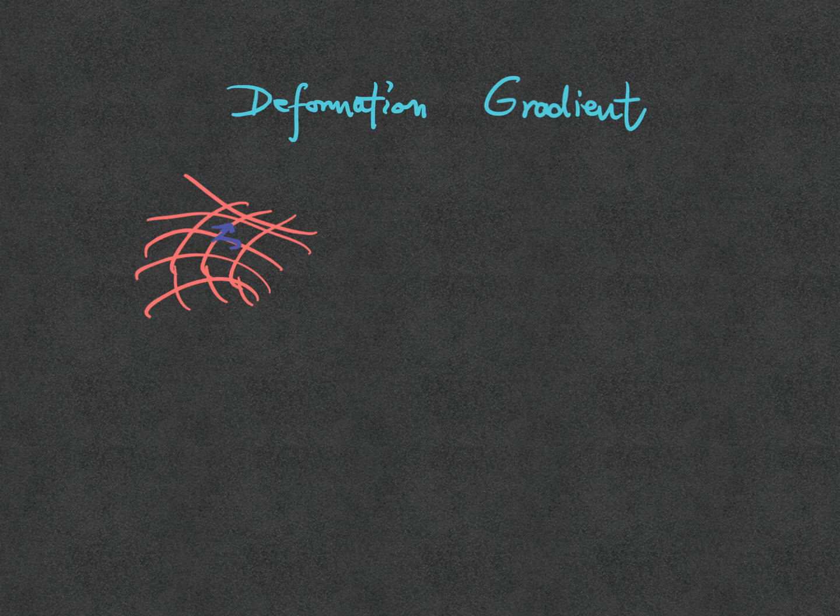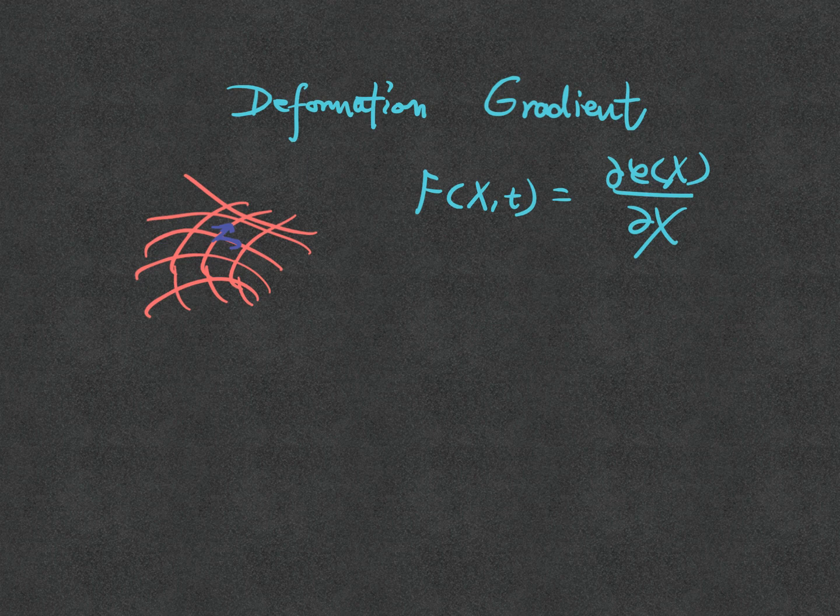Divergence is the trace of it, or actually just summing up those components together. So a deformation gradient tells you what happened at a particular point, at the particular location, what is the relative change of the distance in the neighborhood. Okay, so this is written like this in tensor notation.